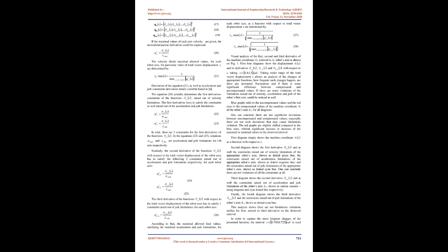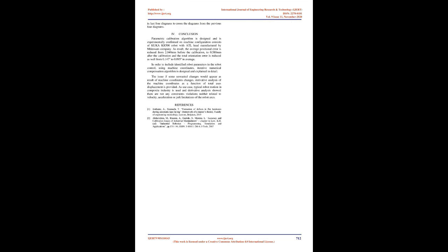Since the tool path is a straight line, theoretically it could be defined using G-code of only 2 points. But in this case, the interpolation between these points is completely left to the controller, and the tool orientation is not controlled as well. That is inadmissible, especially in the case of robot usage in composite tape laying, since then following the predefined position and orientation of the tool along all the path is extremely important.